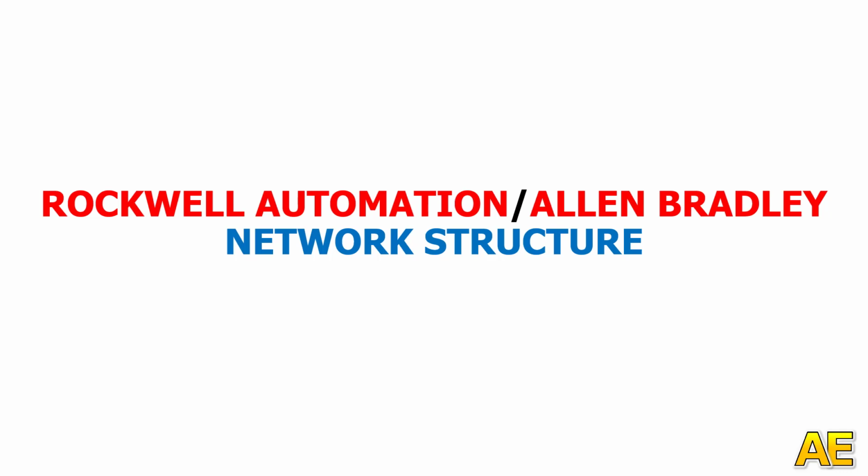Firstly, we need to separate two types of modules based on the location: local and remote. What is the local module? The local module is the module on the same chassis with the PLC CPU, and the remote module is not on the same chassis with the CPU. It can be in the same cabinet with the CPU or in another cabinet on site. Okay, now we come to the structure.